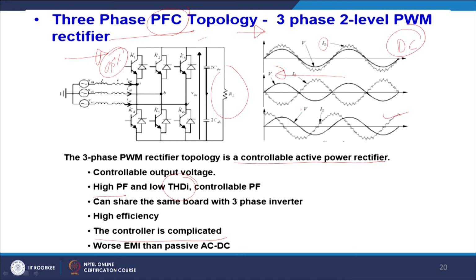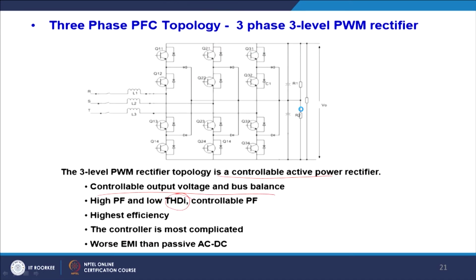Not only unity power factor, if you want to compensate the negative var, you can inject the positive var by proper switching. And control is more complicated.